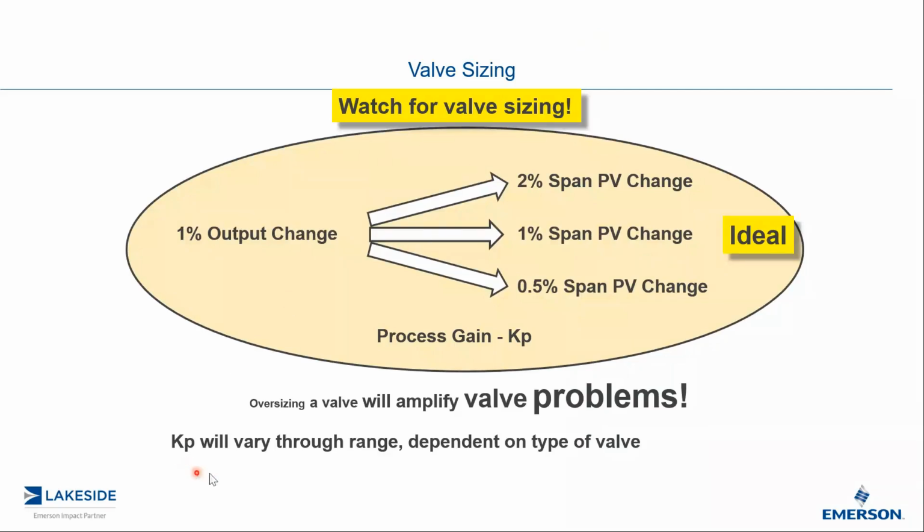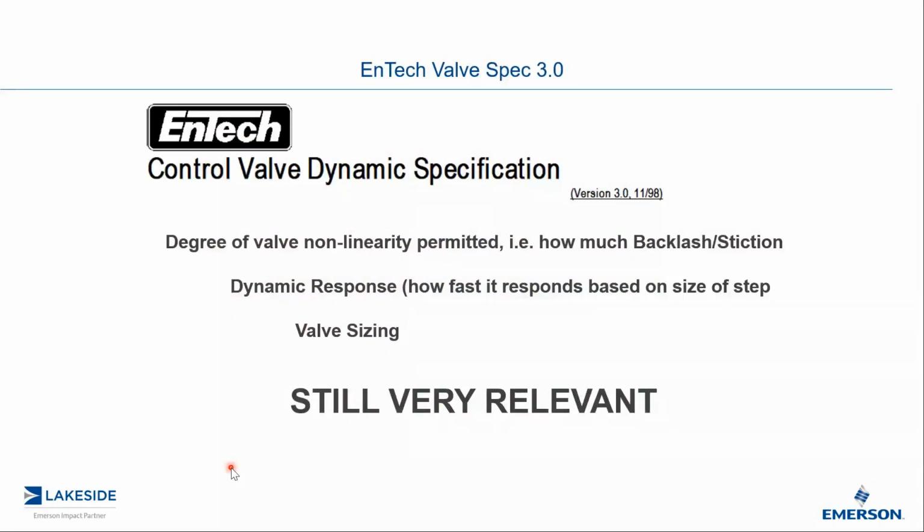We also have to understand, and we talk about this in the control valve part of my webinar, in probably 2 or 3 webinars, how your process sensitivity will change over the opening of the valve based on the type of valve. Then you can start using characterizers and so forth. If you want more information about this, there is an actual valve spec. SNF is now owned by Emerson, but when I was working for them, we were an independent company, and that was part of developing this control valve specification that outlines everything from valve sizing to valve precision and dynamic response. So it's still very relevant today.